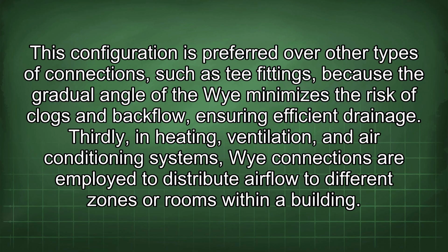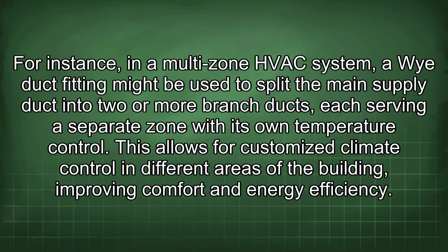Thirdly, in heating, ventilation, and air conditioning systems, Y connections are employed to distribute airflow to different zones or rooms within a building. For instance, in a multi-zone HVAC system, a Y duct fitting might be used to split the main supply duct into two or more branch ducts, each serving a separate zone with its own temperature control. This allows for customized climate control in different areas of the building, improving comfort and energy efficiency.